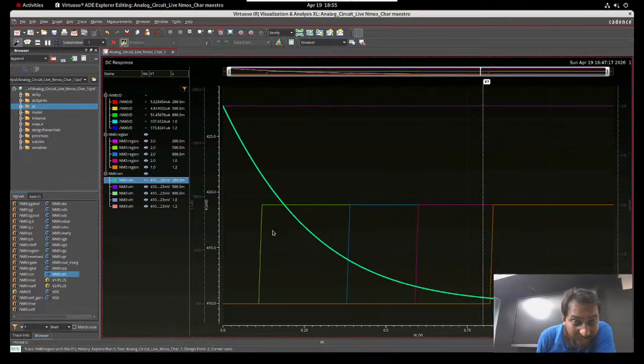But if you are using a higher length, your VTH starts from 420, 427 millivolt. The threshold voltage is 427 millivolt, and if you are changing your VDS, it is not affected. It is nearly about 409, that is at 80 millivolt change. That is okay.